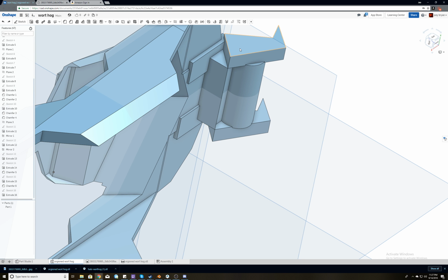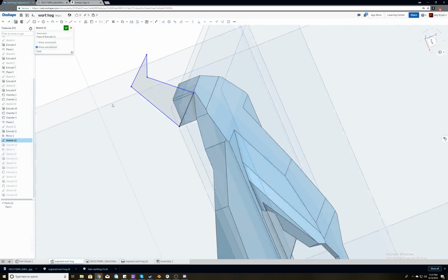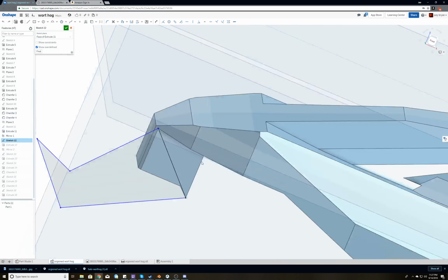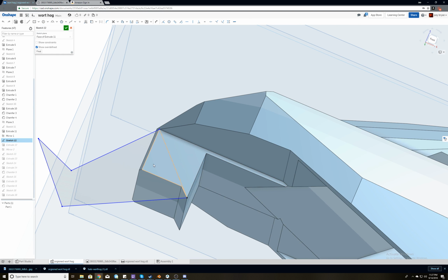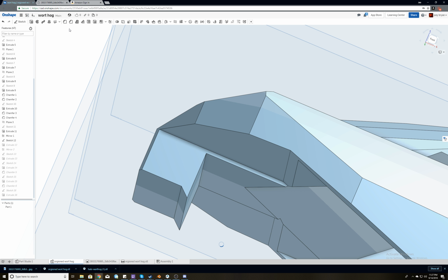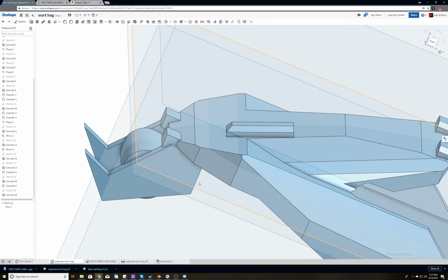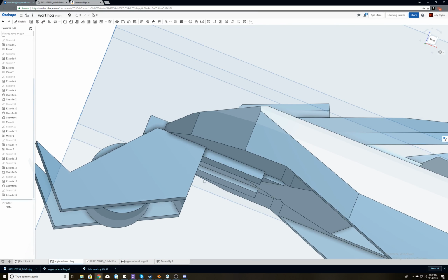So now I'm actually going to find the sketch again. And instead of having it ending on the corner like that, because that's your object area where it actually attaches to the model, I'm going to throw it up there a little bit and simply clip that line. It'll load for a little second, and there you go. That looks like it's going to hold a hell of a lot better. Oh, yeah.